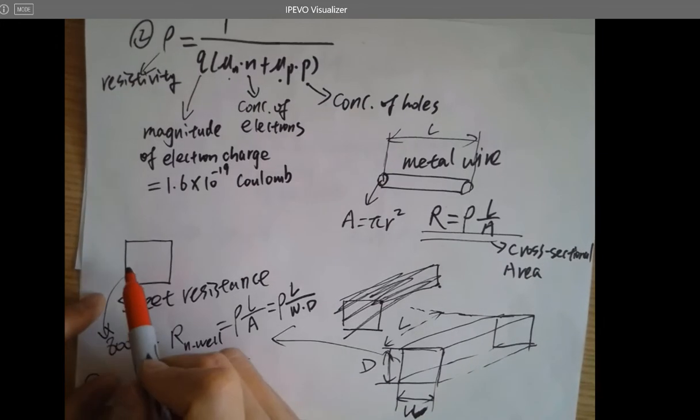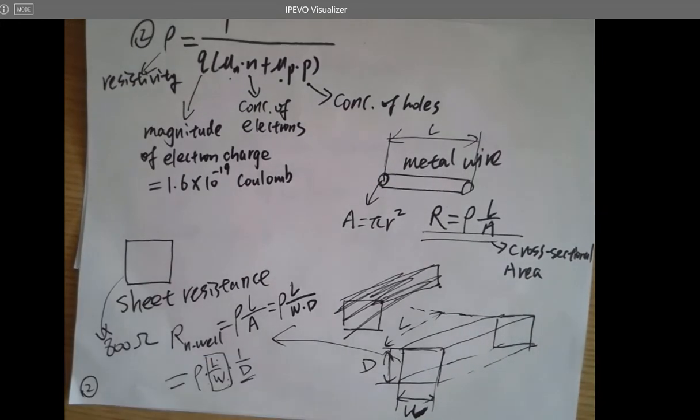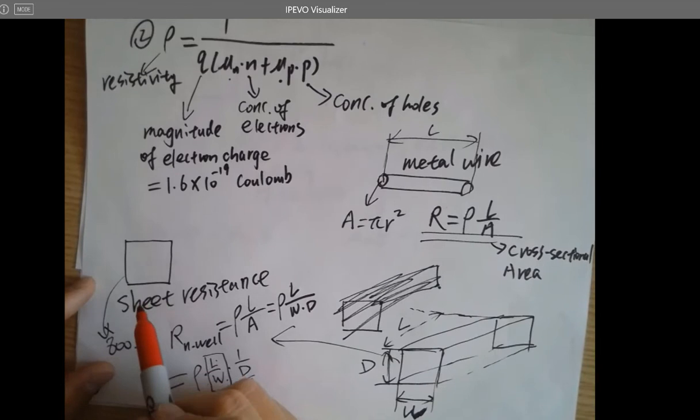It cannot be too small, because the doping machine cannot dope that tiny feature onto the P substrate. You have to follow the feature. I think the minimum size of the N well is 12 lambda, if I remember correctly. Every lambda is 300 nanometers. So 12 lambda is 12 times 300 nanometers. It's the smallest size of the N well. So it can be this.